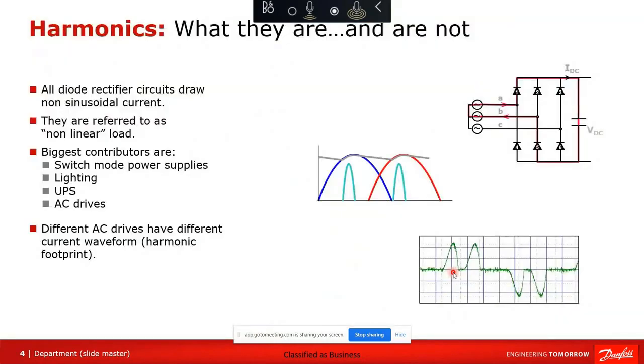So before we get started, or as we get started, it's important to understand how a drive works, and I apologize if there's any redundancy here, if this is a little too basic, but the fundamental of an AC drive is we take in AC power, we convert it to DC power in a rectifier section, we store it in a DC bus, which is basically a capacitor, and then we use that energy and we pulse that energy back out to the motor with insulated gate bipolar transistors, which is IGBTs. It's an industry standard. It's nothing specific to Danfoss. And we send that energy to the motor.